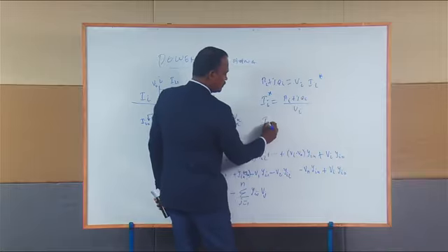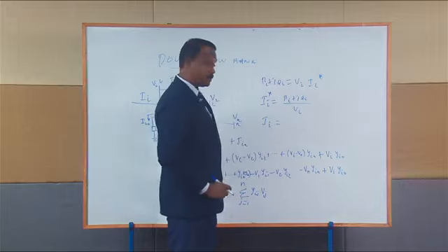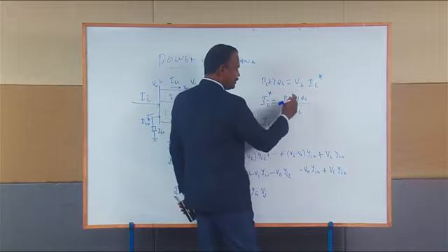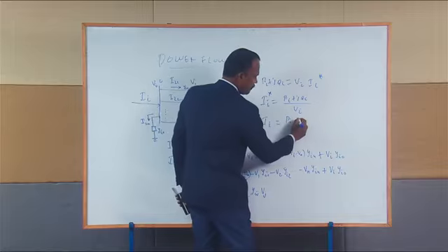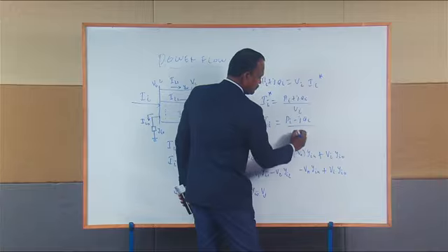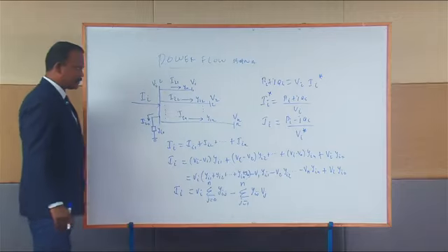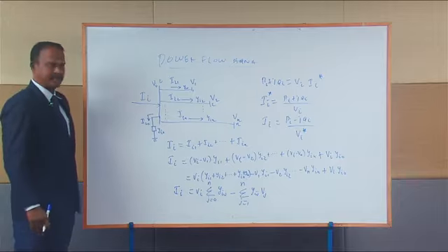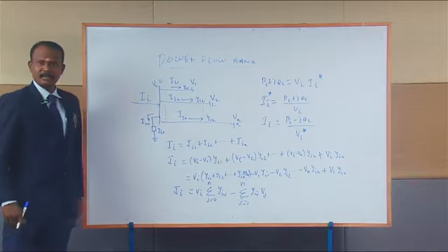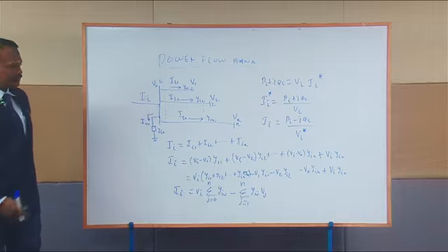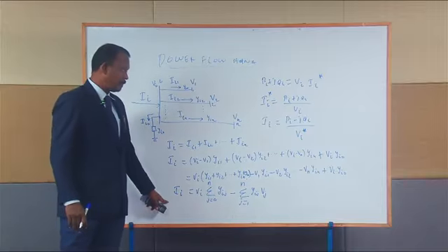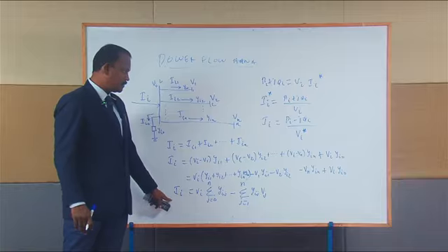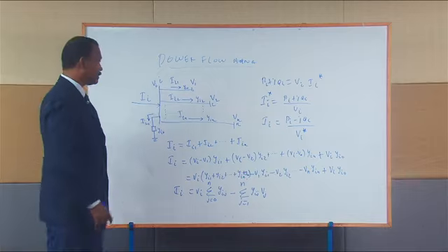To find Ii, take the conjugate on the right hand side, then Pi plus jQi becomes Pi minus jQi, divided by Vi conjugate. So this is the equation for current Ii in terms of the real and reactive power and the voltage. We already derived the equation for Ii, so I can substitute these equations back into the equation for Ii.